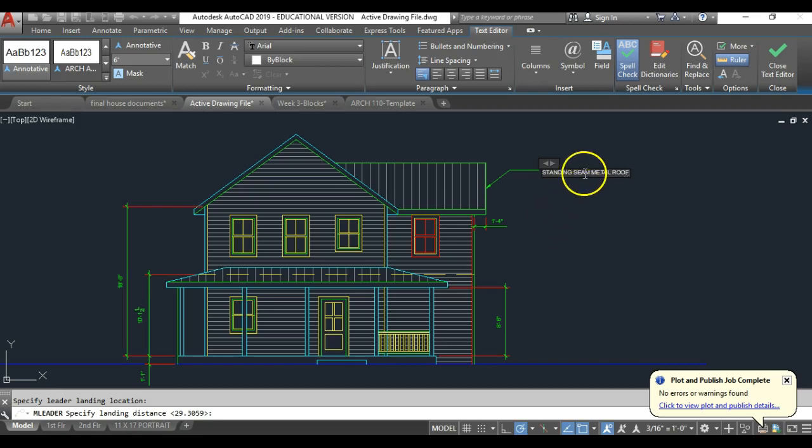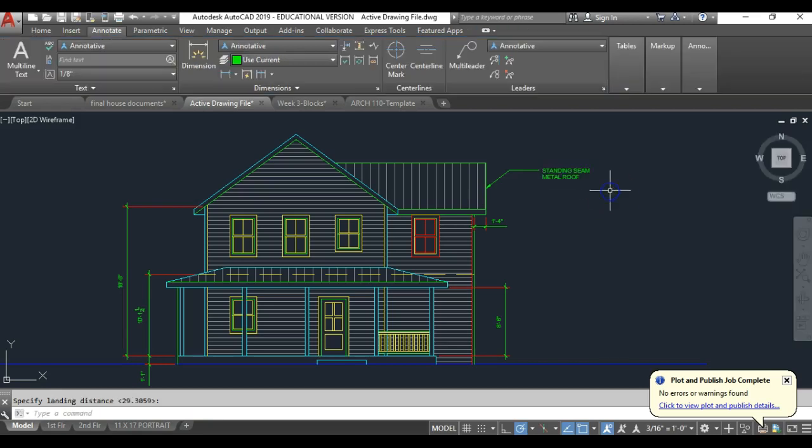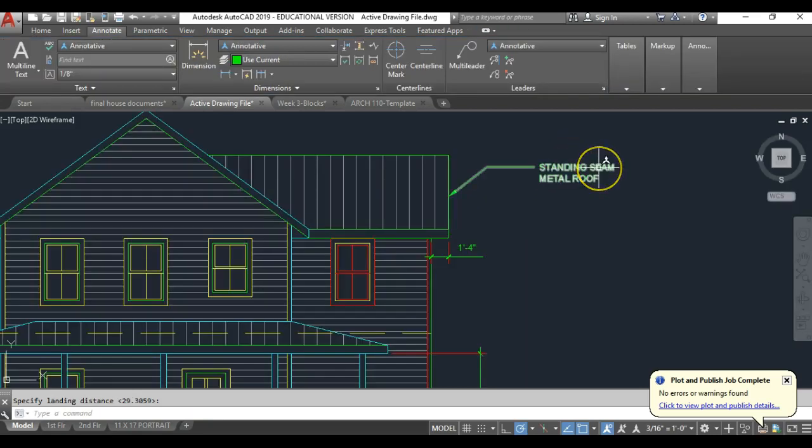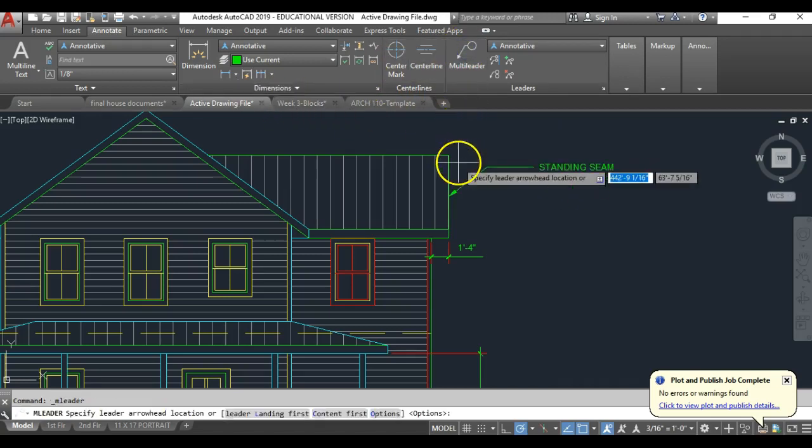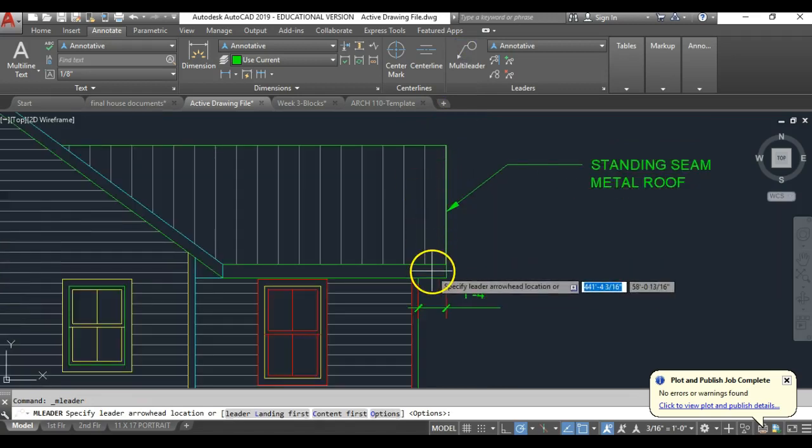And if I want it to return like it returns in the drawing, I'll just click this arrow and pull over to make this about that wide, and hit enter, or it's actually click outside. We can see it automatically makes the notes. And you're going to do that for all the leaders. It's not so bad. So I'm going to go here and start leader line again. I'm going to do the fascia here, so I'm going to click inside.